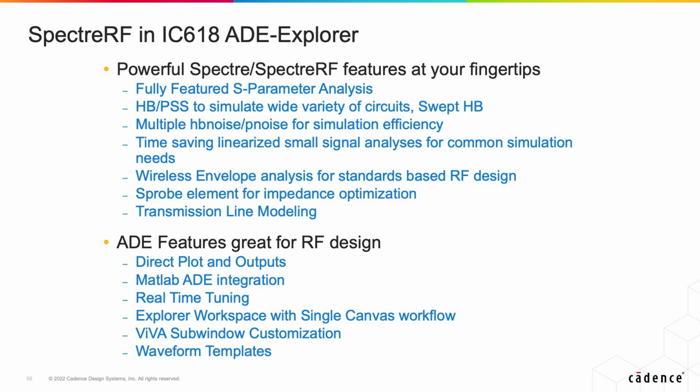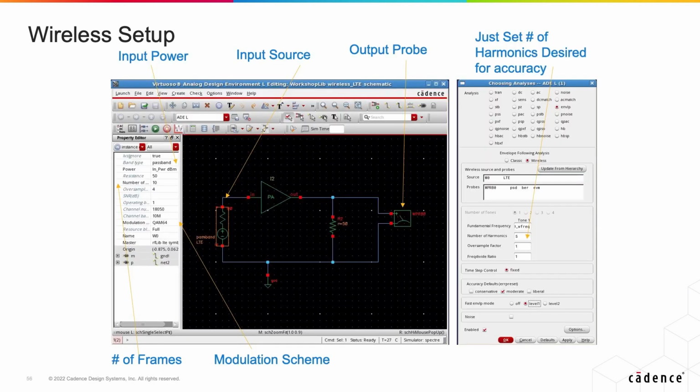What S-probe does is, when you're doing S-parameter analysis of a design, if you insert S-probes at different points, you can see your S-parameter at those points looking left and looking right. But if you want to go a few hierarchies down in your design, you can use something called deep probe with S-probe. Then you can say, I want 3 levels down and here, stuff like that. But if it is at the top level, it's easier. And these are direct plots and real-time tuning. I just want to show you what we have. For me, visual is more important.